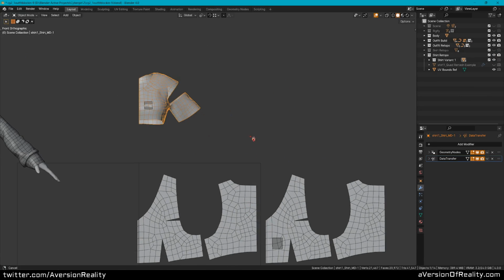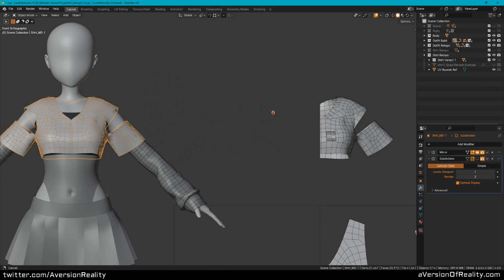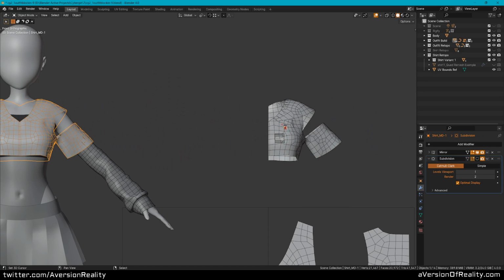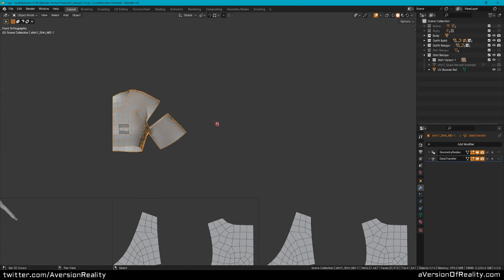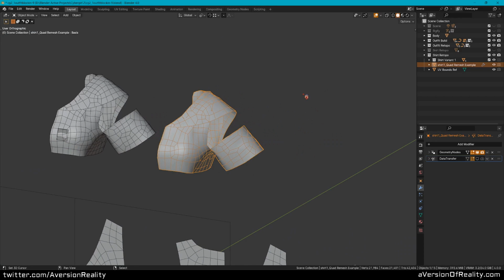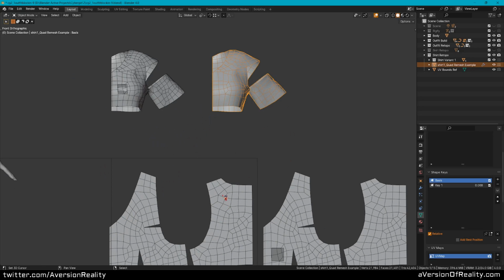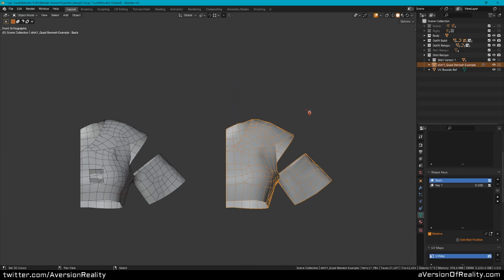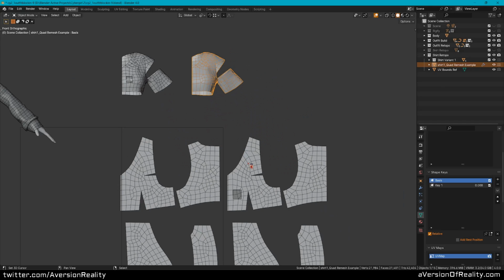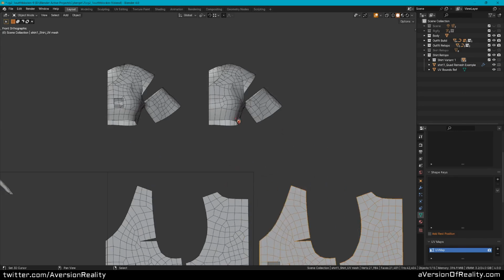Now, a quick side note before we dive into that. I'm using topology that came from Marvelous Designer, but I know some people following this just have whatever topology and whatever UVs from something they've modeled. So I want to remind you all of the quad remesher tool. These UV methods I've been showing assume that your mesh has fairly even spacing. That's why the whole thing where we pin the edges and then hit everything inside with a smooth brush works.